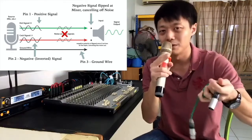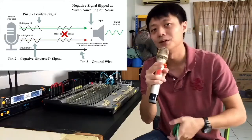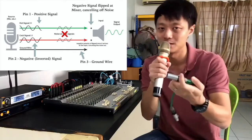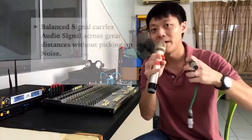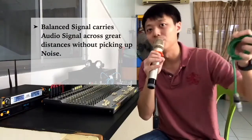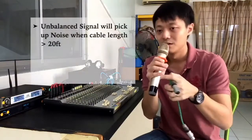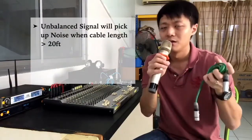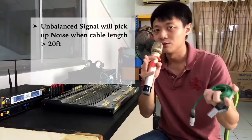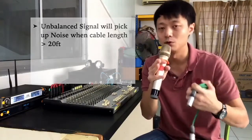This is a very simple explanation. If you want more technical information, you can Google about the difference between an unbalanced and balanced signal. But a balanced signal can carry audio signal for a far greater distance than the unbalanced cable just now. The unbalanced cable can only carry your audio signal at the max 20 feet until it eventually picks up some interference. That's what we call noise.